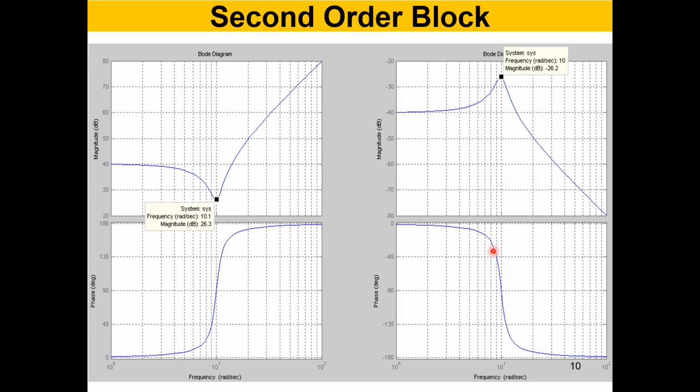When a signal passes through a first order block, a second order block, a pole at 0, a zero at 0, right? Now you have already completed the basic elements, right? So now you can combine these elements: first order blocks, conjugate pairs, combine blocks, right? And use MATLAB and simulate. Use the tf command, use the bode command, and plot them on screen.